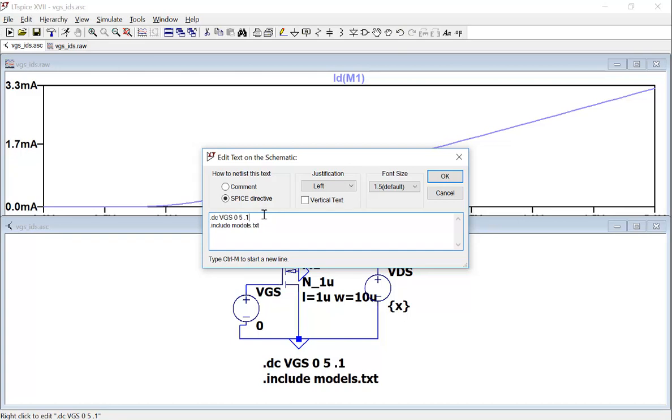And if you want to add a line in the middle, you don't want to directly press enter because it's going to close the window. By default, OK is enter, right? So what you want to do is control enter. Start a new line instead of closing the window, and put a .step as a function, .step. And I believe it's .param, step function for parameter x.